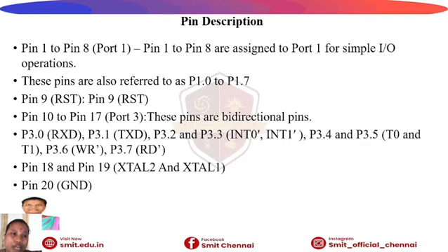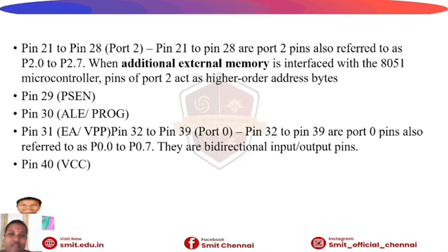And then the next pins are pin 18 and 19, which are the external inputs, XTAL1 and XTAL2. Pin 20 acts as ground, and pins 21 to 28 are port 2 pins, also referred to as P2.0 to P2.7. When additional external memory is interfaced with the 8051 microcontroller, the pins of port 2 act as the higher-order address bytes. And pin 29 is the PSEN pin.